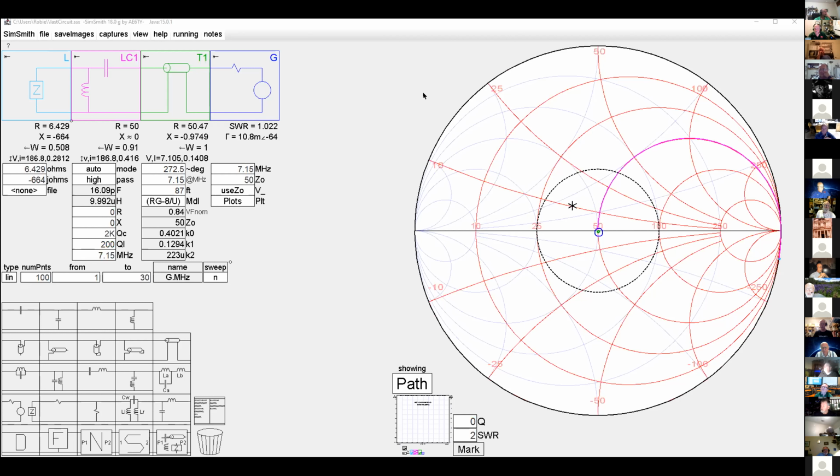That's right. And in the little example that I used earlier, on some of those bands that it won't tune, you might take a piece of coax and add it to the line and see if that helps. Because I showed you how you can increase or decrease the resistance. We'd have to have some numbers to work on that, but we could probably make some sort of recommendation of what to do if you had some good VNA numbers. That's the kind of thing you can do to help solve these problems.